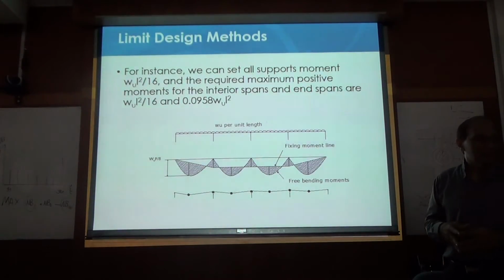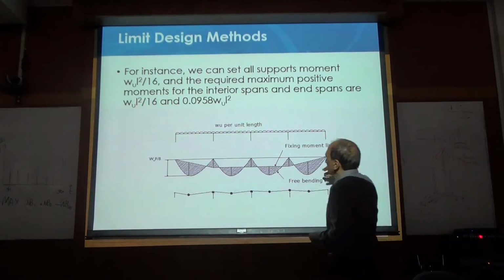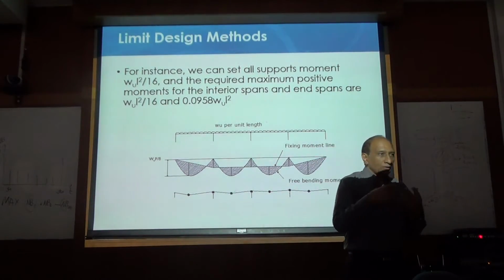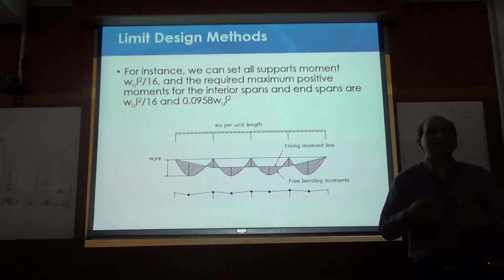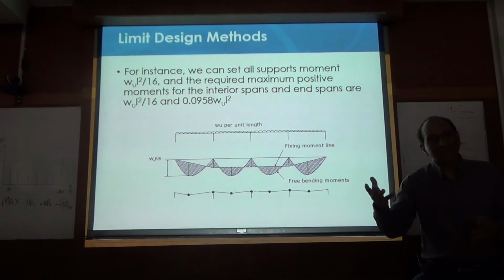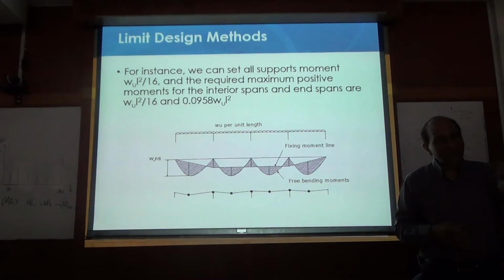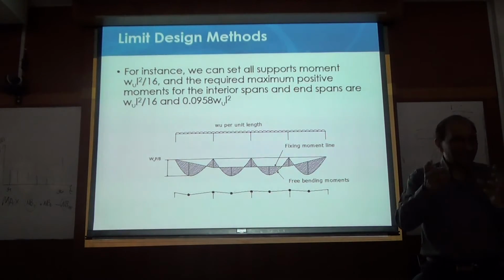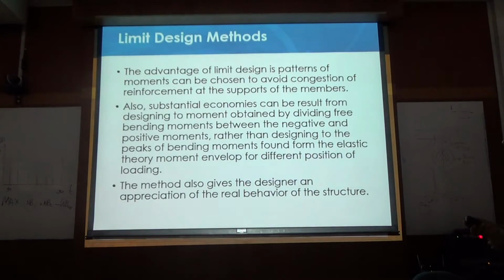This initial elastic diagram and plastic diagram will be different, and we need to study both. What is the moment diagram after yielding, and how can you calculate moment after yielding? From moment curvature, from strains that you are going to measure, because curvature and strain can give you the corresponding moment.